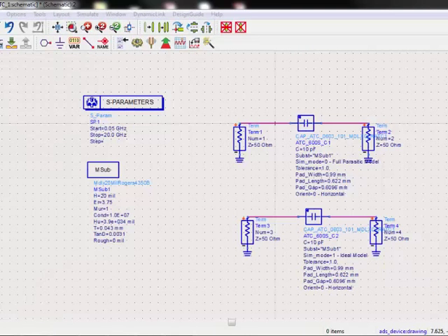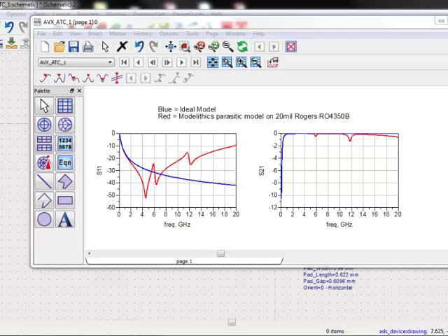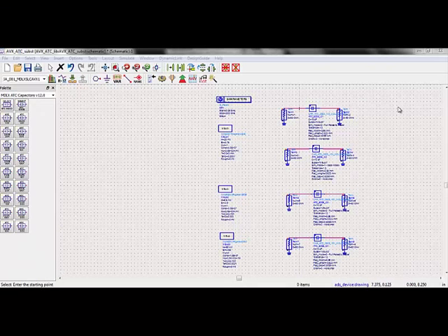Now, the inductors have been replaced with ATC 600S capacitor models. Again, one is set to include parasitics, and the other is set as an ideal component. Here are the results. The parasitic effects are again considerable in the component response. Now let's look at a substrate scaling example.